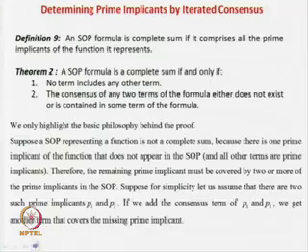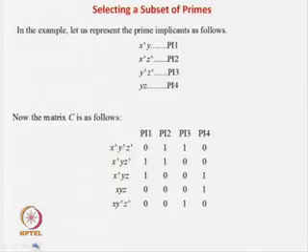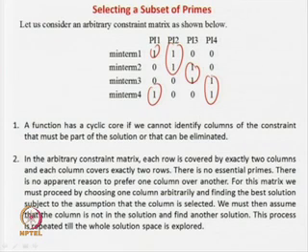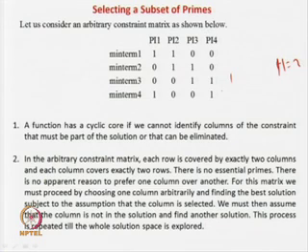There will always be 2 ones in each row. You cannot reduce the matrix further, like if you can see this one, this one, this one and this one. So, this matrix cannot be reduced. So, it is a cyclic matrix. Obviously, nobody can solve it with a single column, because there is no reduction possible and there is no column with all ones. So, what is the lower bound? The lower bound is 1 plus 1, that is equal to 2, because in such a matrix there is no reduction possible and, secondly, there is no single column with all ones.